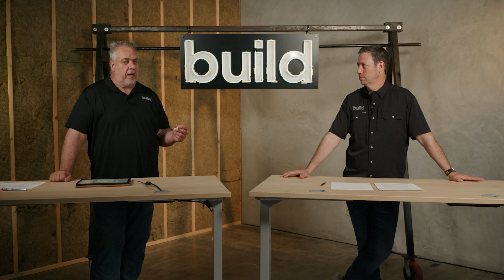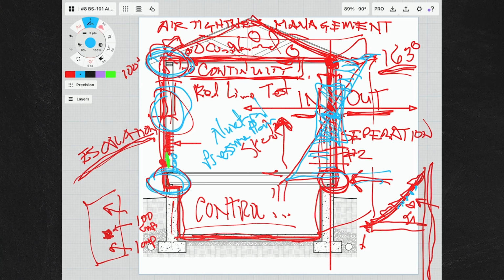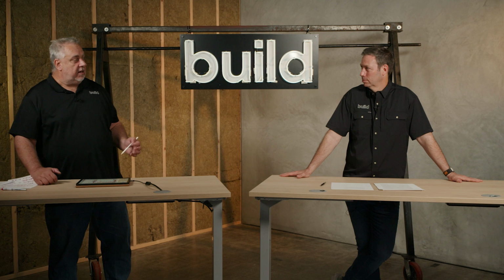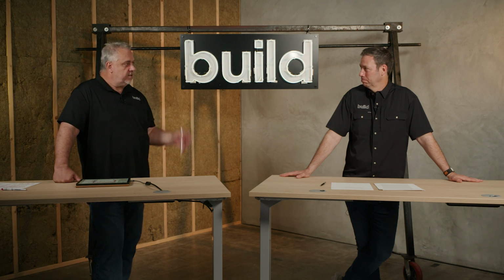Well, what does that mean? Well, plywood is wood. Wood has wood sugars. Those wood sugars mix with that water to make a real, I'll be nice, crappy brown look. Kind of like a tea almost. Like a brown tea. And guess what? Because it's sloping, that water runs right down here. It finds cracks. It comes out here and it drips off of the fascia. But when it does it, it leaves that residue on that fascia board and it creates those tiger stripes.